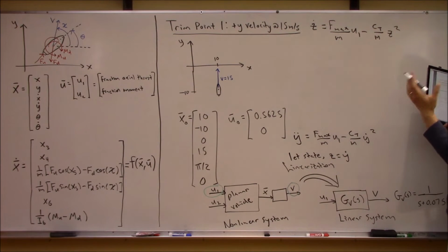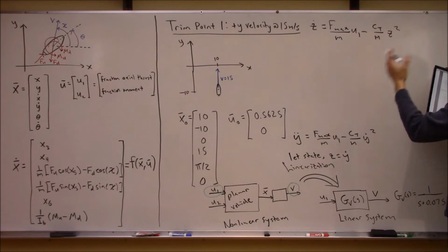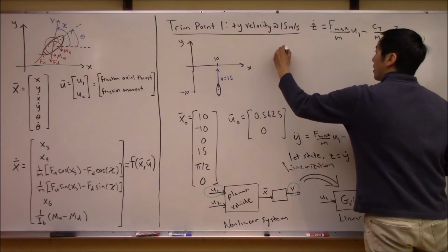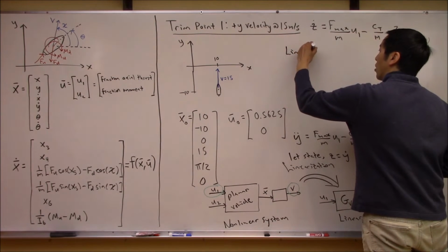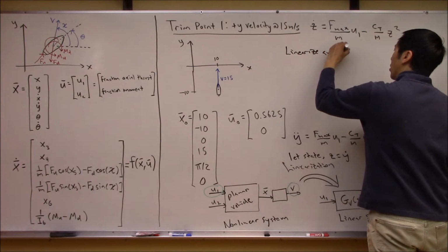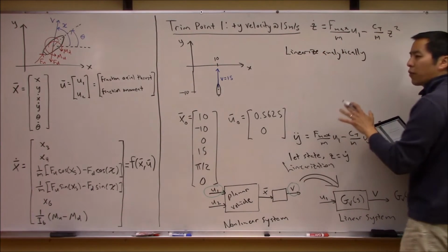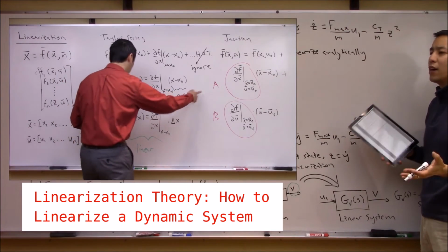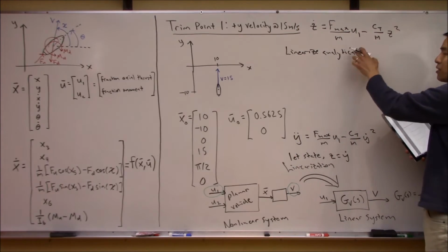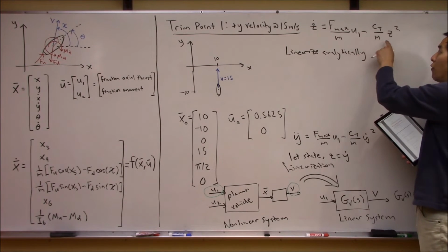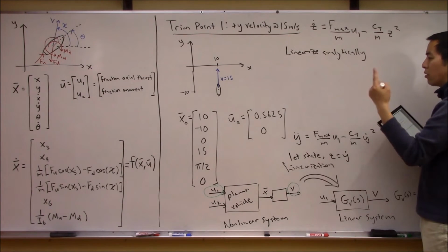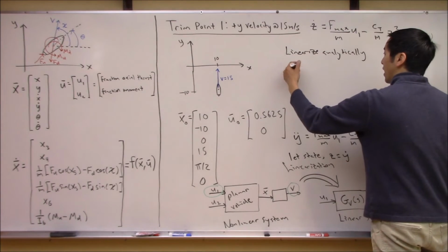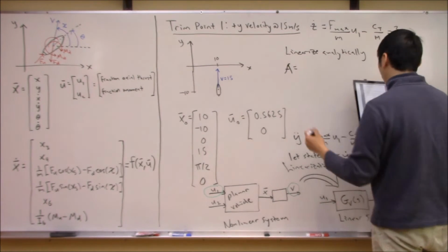Okay, so what I want to do now is let's go ahead and linearize this about a given operating point. So to linearize analytically, right? We talked about this actually in one of our other videos where we talked about performing linearization via a Taylor series. You're basically doing a Taylor series expansion of this differential equation about the operating point that you're interested in. So the A matrix in this case was just your good old friend the Jacobian, right?